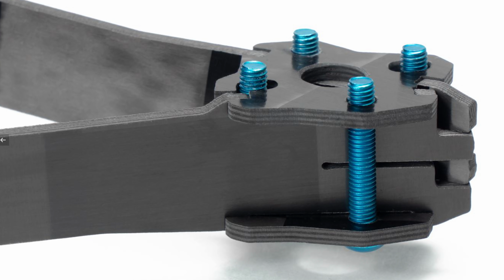Yeah. And a cool thing that we haven't actually shown is how we get the tolerances correct between all the parts, so that we can get the parts from one batch to fit into another one. And because the nozzles in this water jet machine wear, they last for like 1 day or something like that. Then they're worn out. And during this day, this nozzle gets bigger and bigger. So you need to compensate. You need to rig this to compensate for it. So what we've done is that we made our own fixed guide that measures the width of these holes, like a tool.